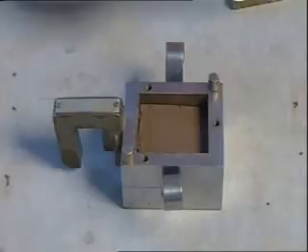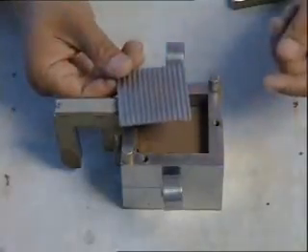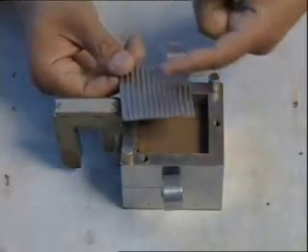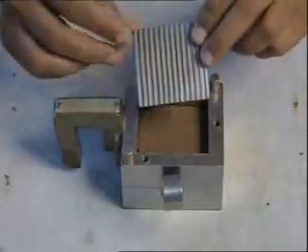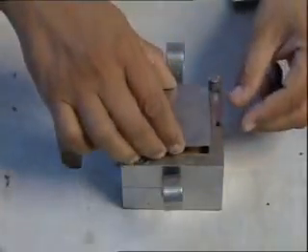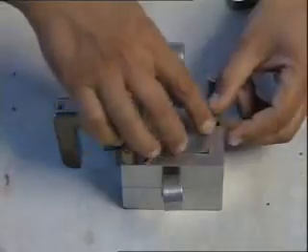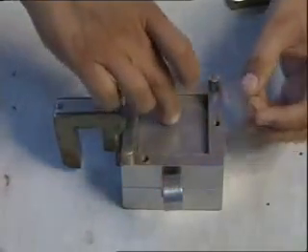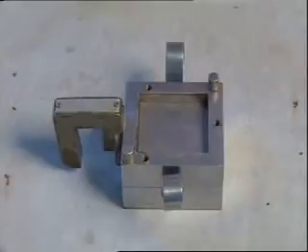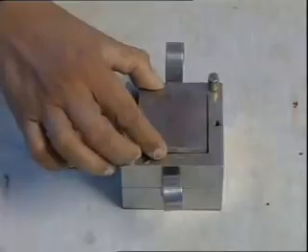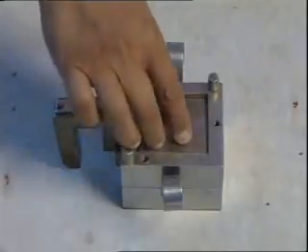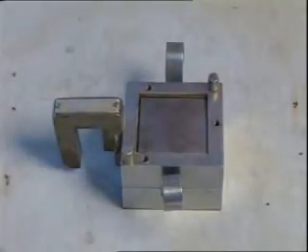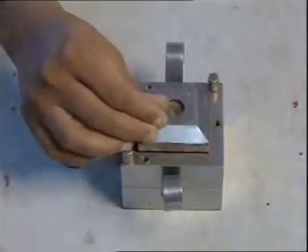Over the top of the soil sample, now place another grid plate without perforations such that the grids are perpendicular to the direction of shear. Slightly press this grid plate evenly so that the grids are buried into the sample. Now place another metal plate over this grid plate. Place the loading pad on the top of the metal plate.